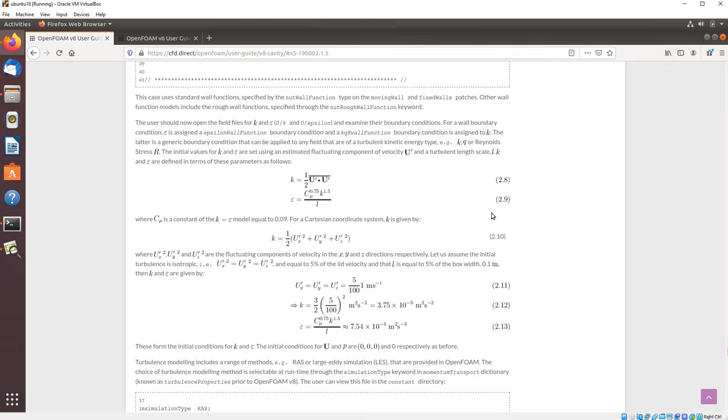Well, this is written here actually. It's a bit more complex in terms of theory to explain. You should read that very carefully, because this is important and is generally something that new users don't try to understand too much in detail. But if you choose wrong parameters for the initialization of the turbulence, your model is just wrong.